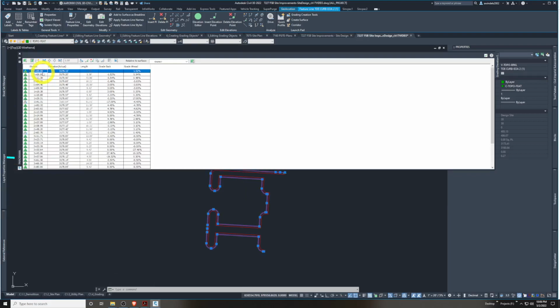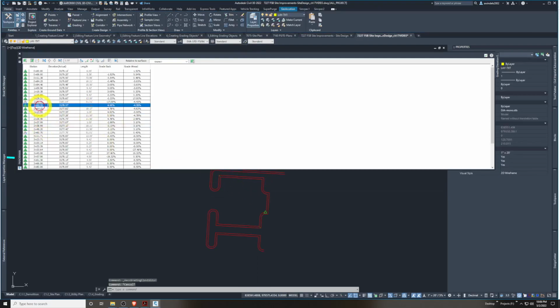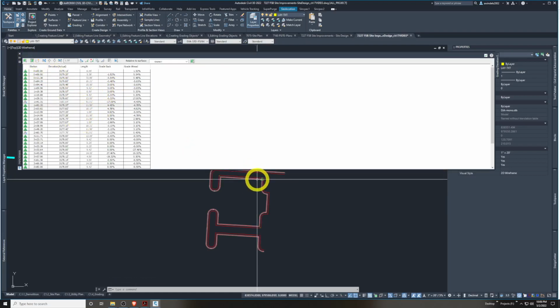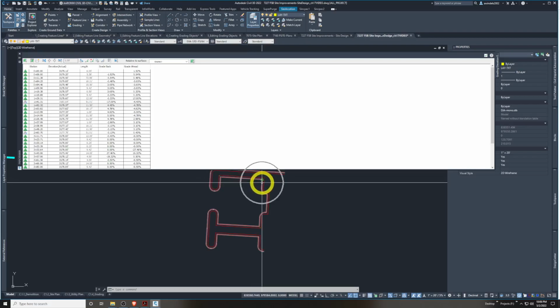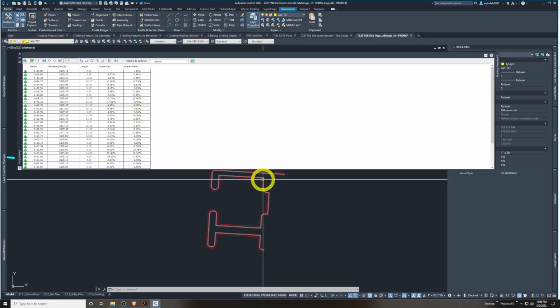It's going up. As we go across this, you can see them highlighting. I'll hit escape so you can see them better. We're going up and down in the stationing as it goes up and down here. We have elevations at each point. So that's our deep tabular editing. And every point, you've got a grade back, upstream, and a grade ahead, downstream. And you also have a station and an elevation. So four entities, and between 2 points creates a length, right? So there's certain things you can edit in this fashion too as well.